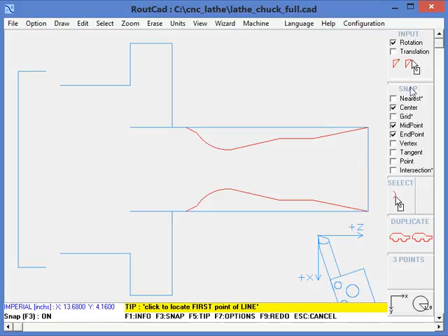So now the snap options are midpoint, endpoint. Basically, we're only going to be snapping to endpoint, but we can leave the other one there. That doesn't matter. So we're going to click on the first line that we want to draw, another keep out of routing line over here. There's also another line missing over there. We click and we click the right mouse.